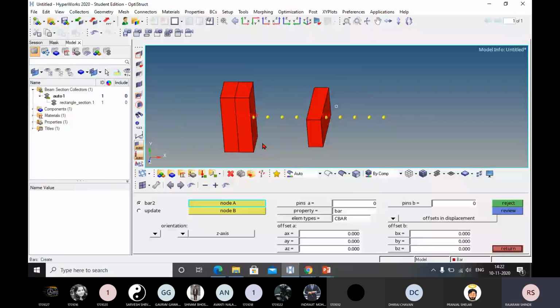Okay. Now orientation and why it is important, I will tell you. See here, if you take this orientation and if you apply bending load like this, that means in the y direction, then you will get the different stresses. And if we apply the same load on this orientation, your stresses will be different. Here you will get the more stresses, here you will get the less stresses, because distance of neutral axis from top and bottom is different. Okay, do you agree with this?